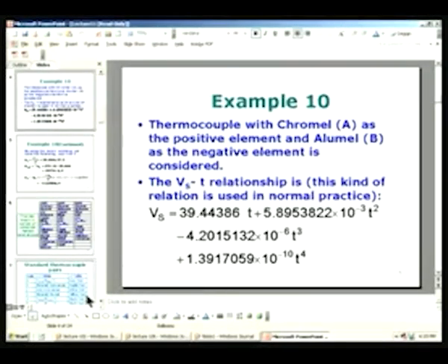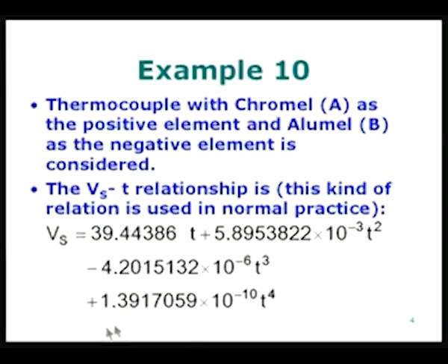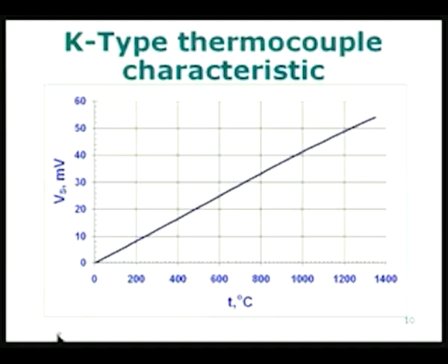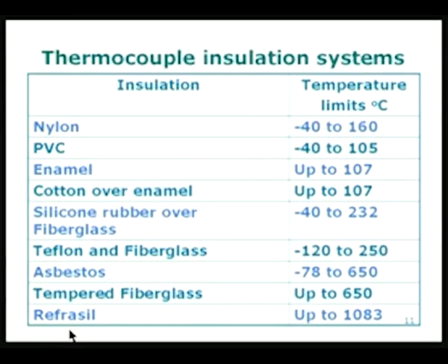So, with this background, let me go back to the slide show and look at some other practical aspects, whatever is possible within the next few minutes available to us in this lecture. The thermocouple contains, as you can see, two wires, and these two wires should not touch each other anywhere except near the junction where the two materials are in intimate contact. If you remember the circuits which we were drawing all the time, there were two junctions and the wires were shown separated.